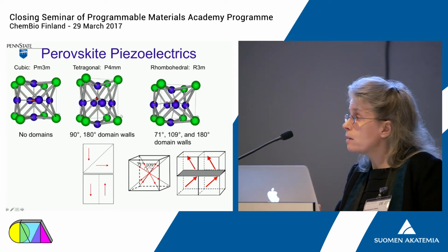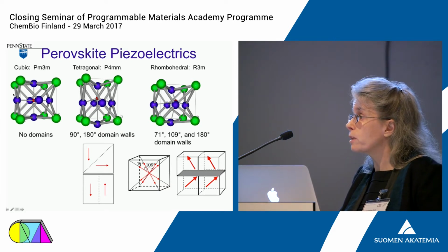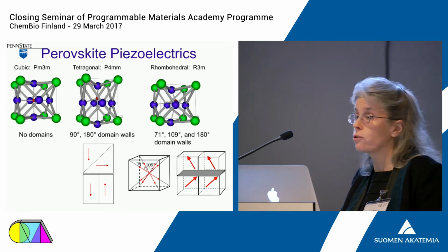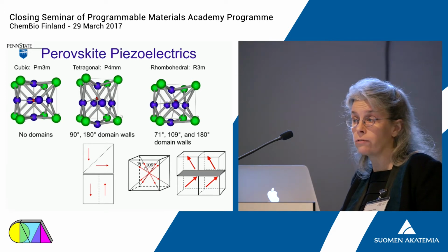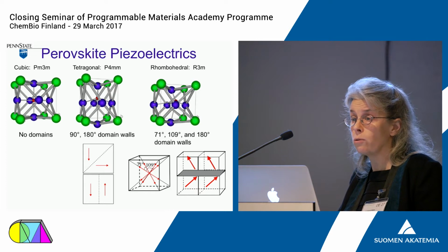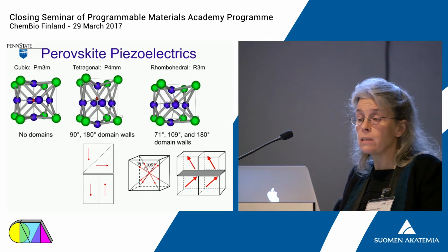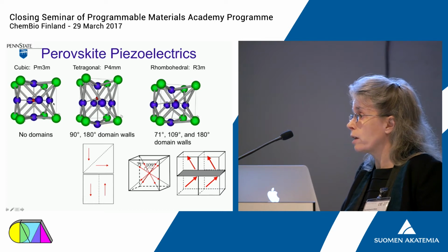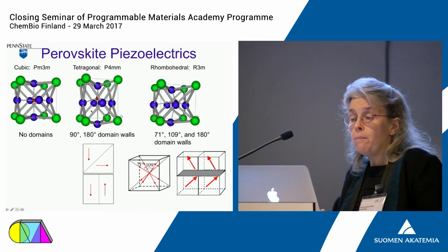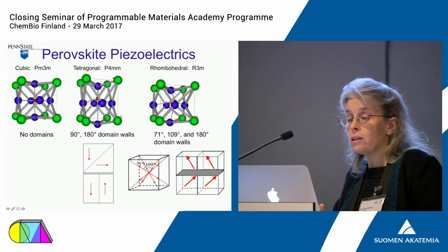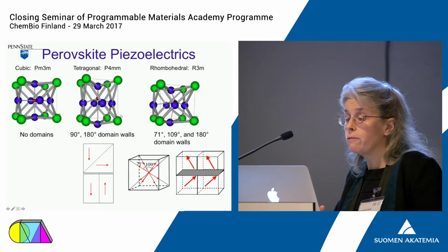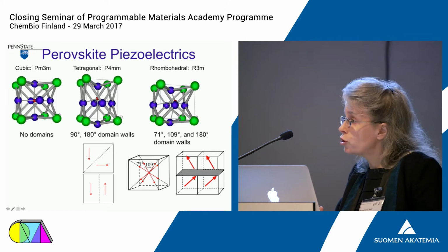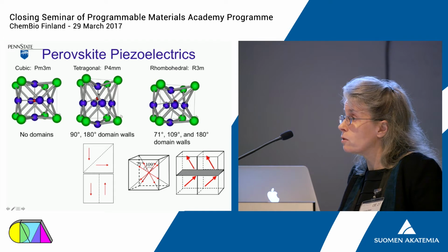At elevated temperatures, this is a centrosymmetric crystal structure so that the center of positive charge and the center of negative charge are physically co-located, with the net result that these materials have no polarization and no piezoelectric response. But at finite temperatures, typically below around 350 degrees in the case of lead zirconate titanate, the atom that should be at the center of the unit cell displaces from the center of the unit cell.